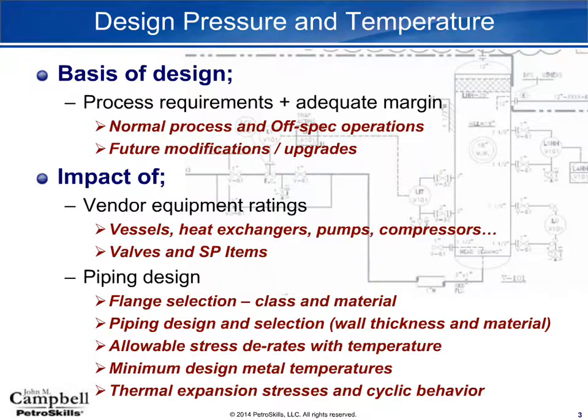When we start talking about the piping design, then there is a lot of details such as the flange selection, class of material. I'm sure people have seen the flange selection tables, and we're going to be touching base on these here this morning. As well, we're also going to be jumping into the piping design and wall thickness selection, how the derate for temperature occurs on materials with regard to allowable stress.